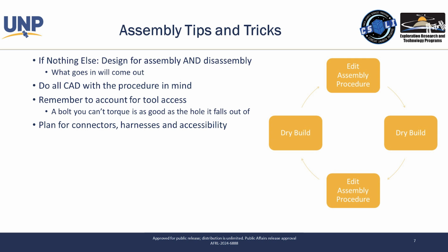Another thing that's common in assembly is we forget connectors and harnesses, that you actually need to be able to plug something in and unplug it. Like your USB connector, once it's mated, is quite a bit smaller than when it's free, and you need that free straight path access to be able to plug a USB in. You can't just start with it plugged in, like throwing your laptop into your bag with something still plugged in.